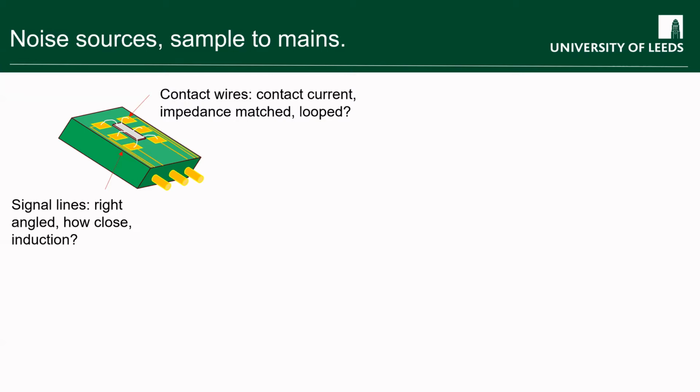Remember again that you've got to think about the characteristic impedance. And if you get that wrong, you're going to end up filtering your own signals out. So, for example, one of the very common things is that you're designing a system to measure a high resistance sample, and then you have to remember that the capacitance plus the resistance of your sample make a rather nice filter, and that's going to limit the bandwidth you can use to do your measurement with. So you have to think really carefully about the combination of the measurement apparatus plus your sample in terms of its electrical performance.